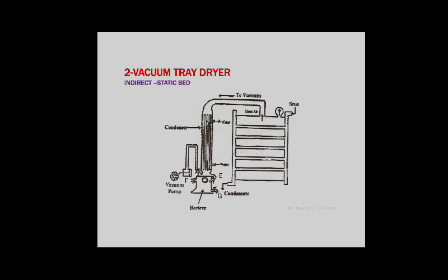Advantage: it's simple, cheap, and can be used for storage. Disadvantage: requires large surface space, high labor, long drying time. Solvents can be recovered from the dry air. Variable temperature, used for thermostable only, not used for dusty material. Used for thermostable granular material, individual articles like flasks or beakers.